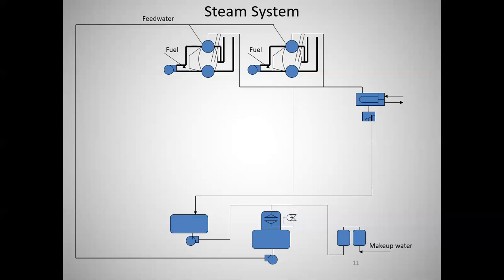There's leaks, there's this, there's that. Sometimes some of that steam gets direct injected into products. It gets contaminated and it doesn't get cleaned up. And so you just dump condensate. Sometimes it's too far. A big plant, it might be 1.5 miles down there where that steam gets used. It's just too far. We're not going to bring it back. They just dump it out on the ground, pour it in the sewer, whatever. So you're not going to get it all back, and so you're going to have to put makeup water in the system.